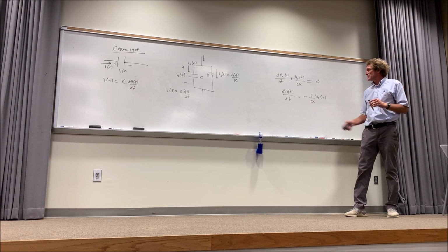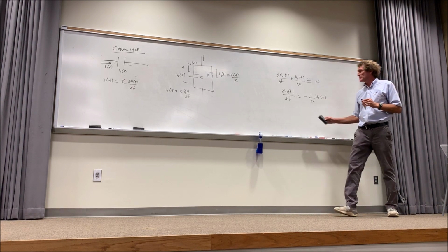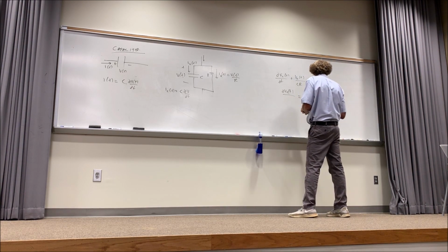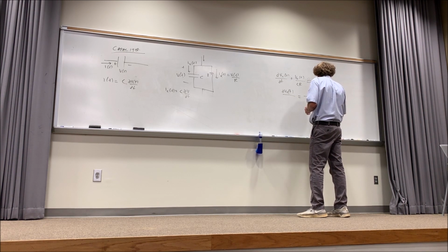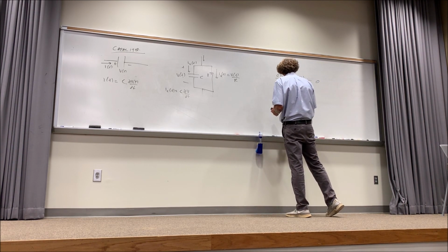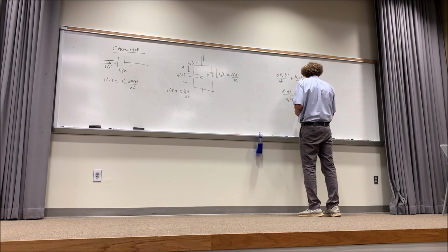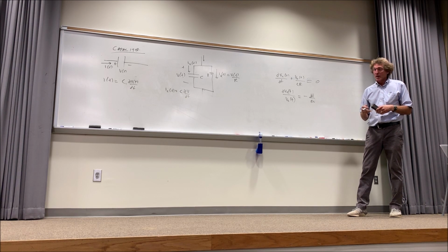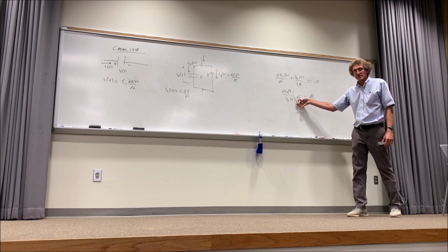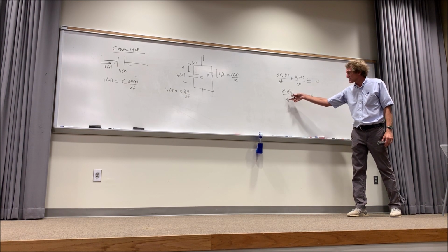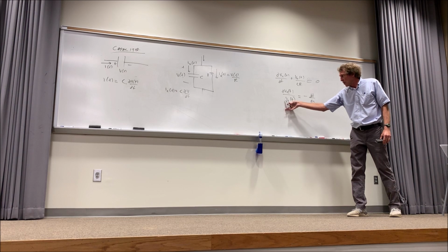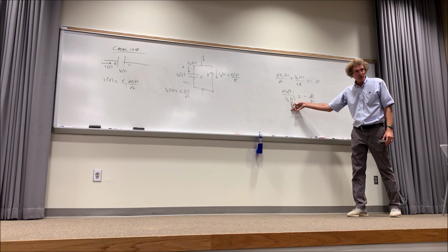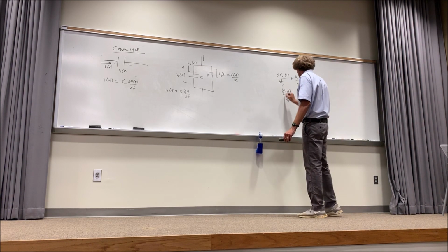Now, when I get this, the way I solve it, multiply both sides by dt and divide by V_C of t. All right? Now, what is 1 over x dx integrated? Natural log of x, right? This is like the differential of v over v integrated is natural log. Do you follow me in this class? I did it this way on purpose to make it easier to see.